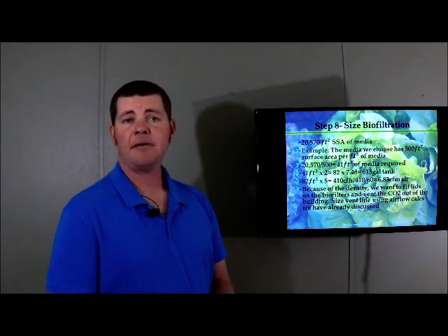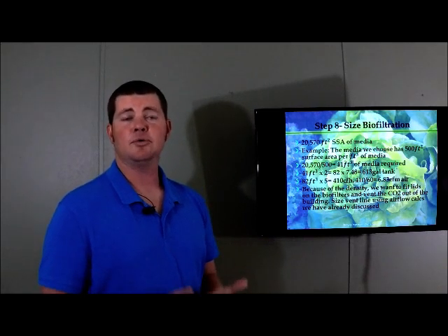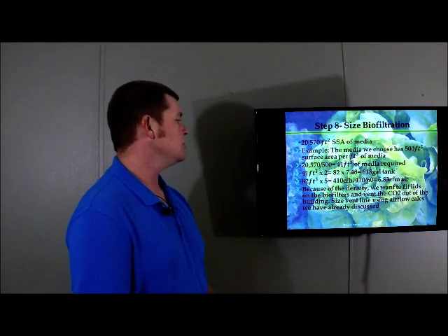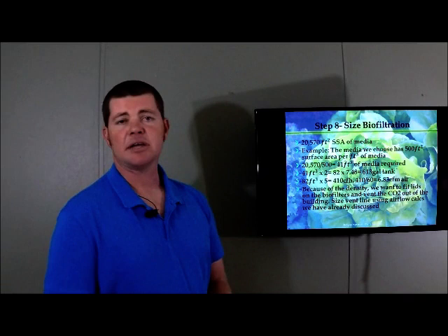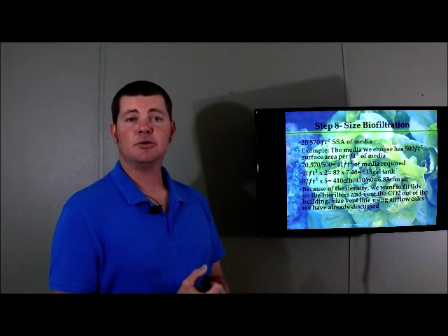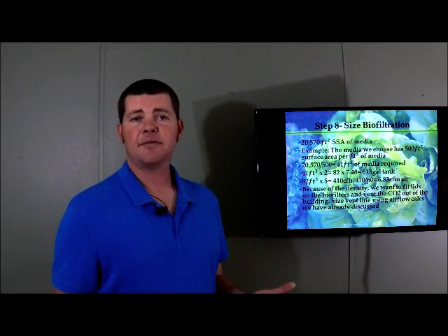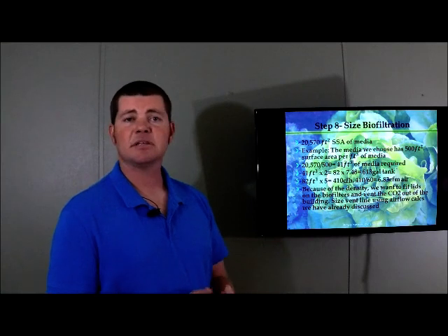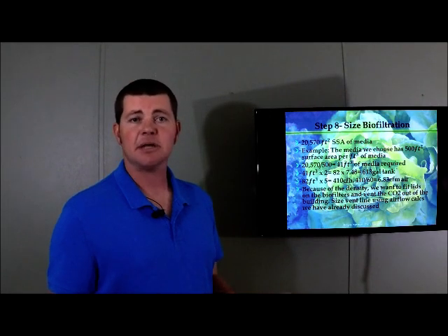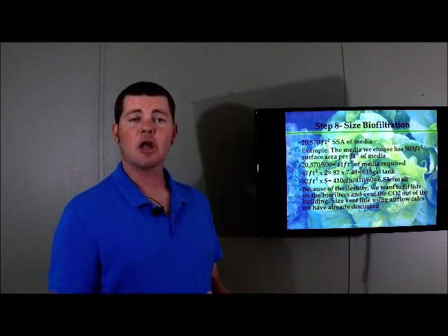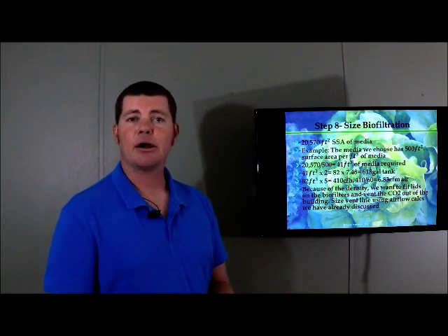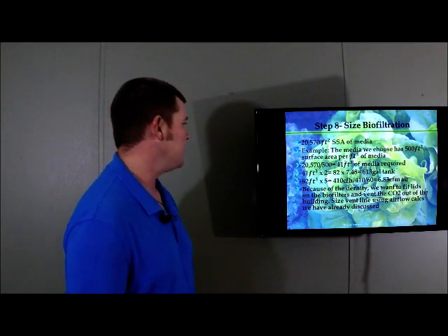Because of the density, we want to fit lids on the biofilters and vent the CO2 out of the building. We're above a half pound per gallon. We want to degas CO2 out of the building, okay? Size vent lines using the airflow calculations we have already discussed. So you have 6.83 CFM injected into the biofilter, right? Well, that's your airflow. So with the PVC line coming out of the top, going out of the building, that's the airflow going through that line. Just size it appropriately so you don't have any major friction losses and you're not pressurizing that biofilter to try to get air out of it. It's not very hard, but that's how you do it.